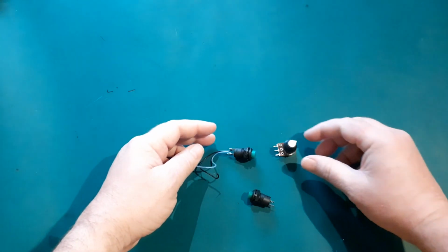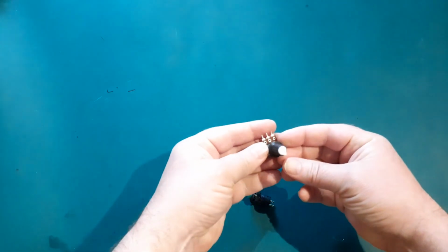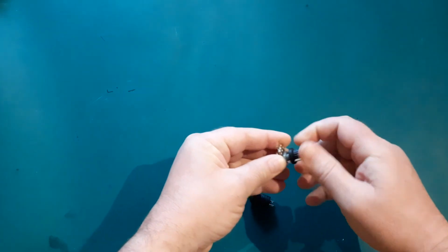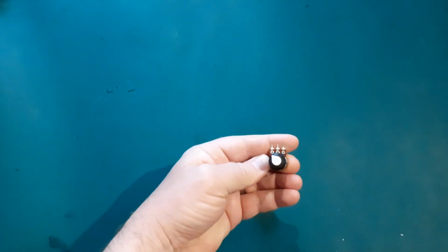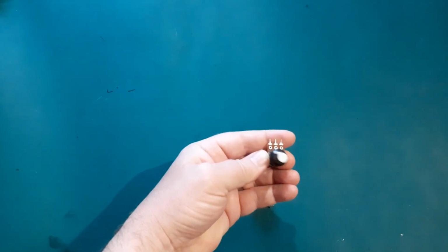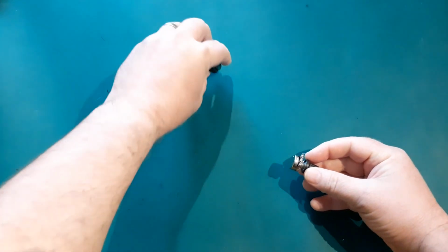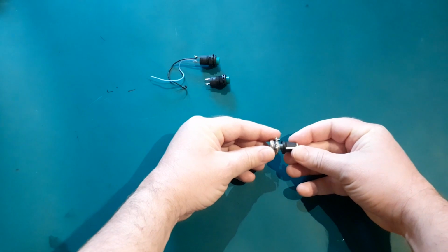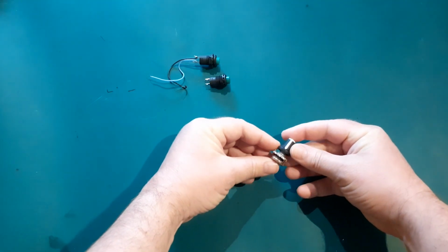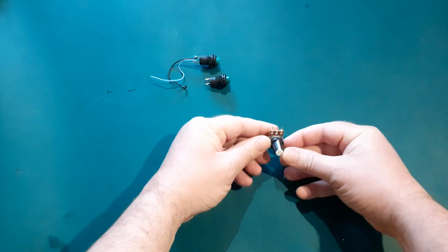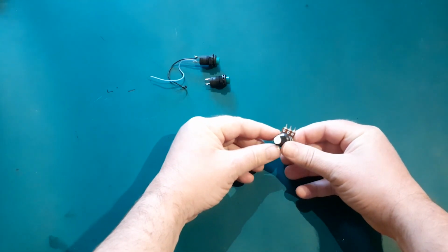Here it is, a simple potentiometer. The value of this one is 10k, but you could use 100k or 1 meg. It makes no difference to how this will work. The only thing I would say is don't go lower than 10k, as the lower you go, the more current will be used needlessly.